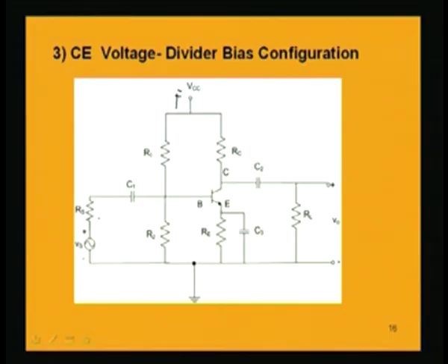So, always we have to proceed with the first principle. That means, if we want to find out the input impedance, it will be Vi by Ii. But one thing to be noted here is that we will be considering the source and the load outside the purview of this two terminal network. That means, the input terminals will be having the source resistance and source outside, and the output terminal will be having the load resistance outside. So, this point has to be remembered, and the whole network will be in between these 2 pairs of terminals, input and output, 1 1 dash and 2 2 dash if we name it.